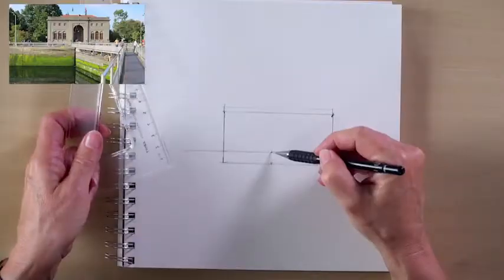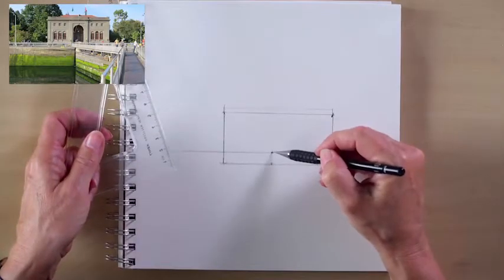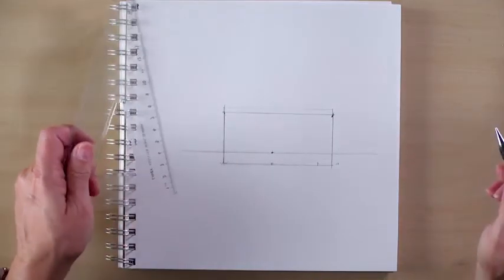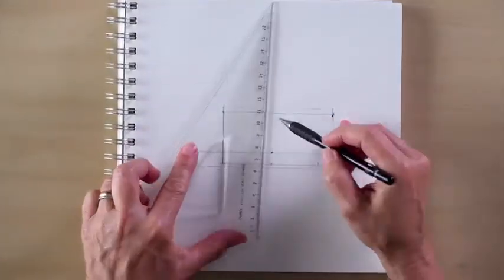And then it looks like my vanishing point would be more or less straight in front of me, maybe right about there. So those are the 3 steps. Draw the big shape, extend your lines and find your vanishing point, draw your eye level line all the way across your sketch. And those are the essentials that you need to pretty much sketch any building. So let me keep working on this a little bit and show you how I fill it out.